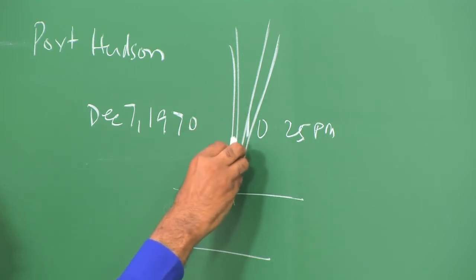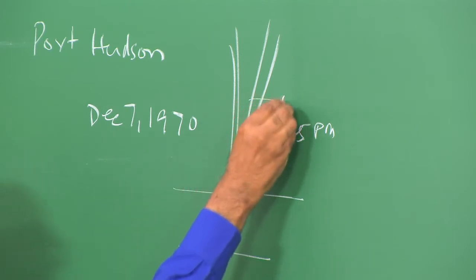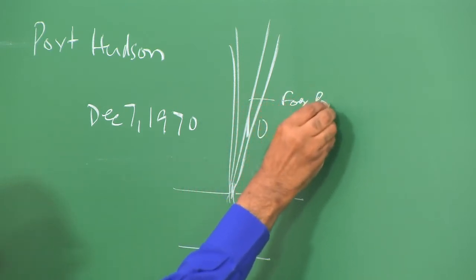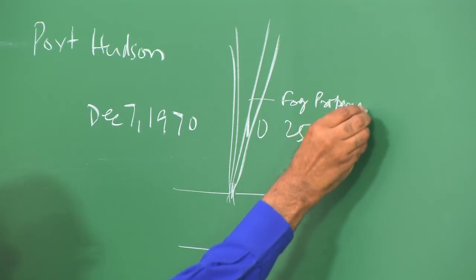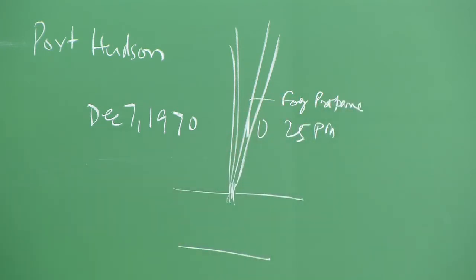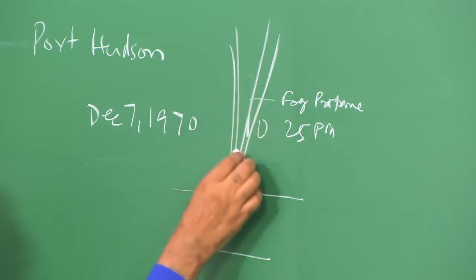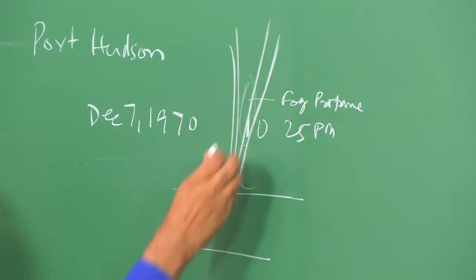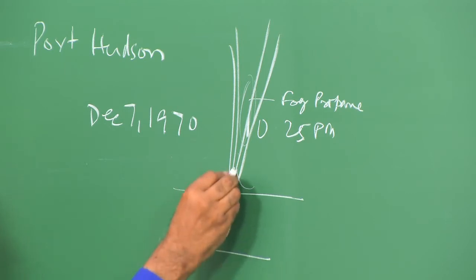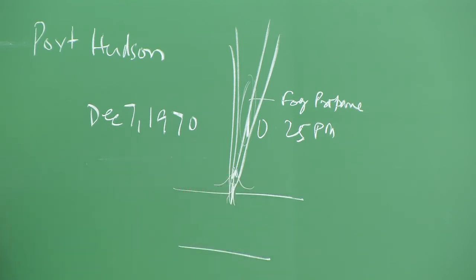That flashing absorbs the latent heat, and you have a fog of propane vapor formed. In addition, it also entrains some air, and therefore you have a propane-air mixture being formed at the zone where the burst takes place.